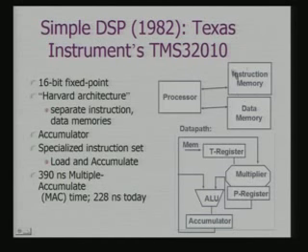In fact, there is a separate instruction memory and separate data memory. Why? Because obviously for each tap I require data fetch and multiple data fetches, so I would not like to have a bottleneck in memory data transfer. So the choice has been Harvard architecture.